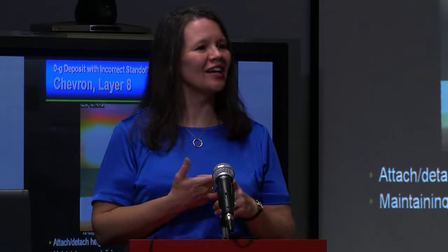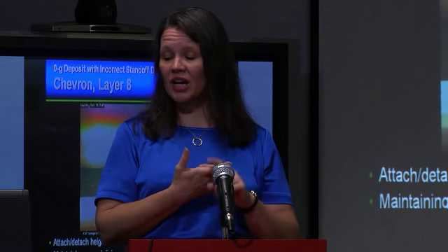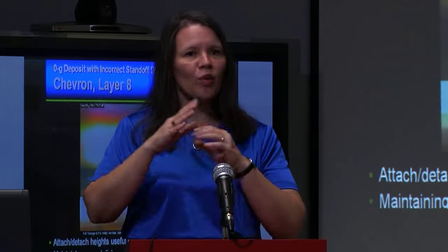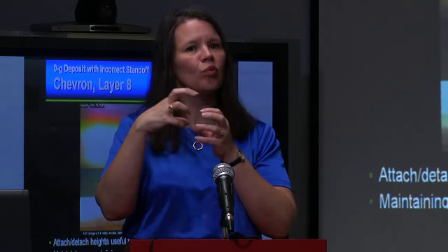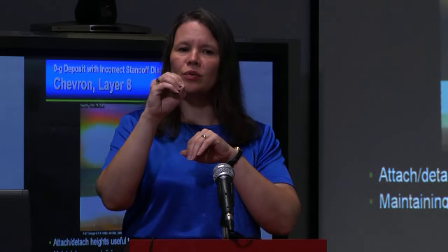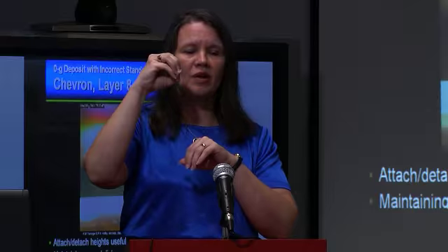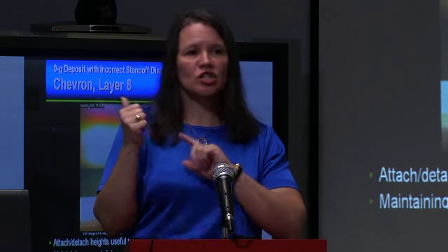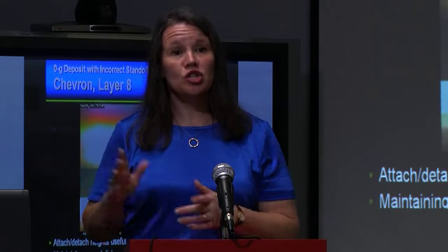So yeah, we only had planned on doing 8 layers, and so the lesson learned is maintaining the correct height is critical for us. Maintaining the correct height is important for process control. But I think that in this one series of 8 15-second clips, we learned more about how the process is actually behaving and learned more about the molten pool dynamics with the difference between the surface tension, which is causing it to ball up on the end of the wire feeder, and the wetting forces, which is pulling it down onto the plate. We learned an awful lot just in this one sequence, and it took us a long time to get there.